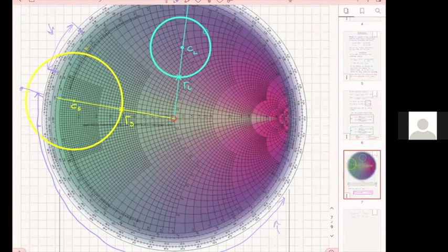Is that clear the way I described it, or was it not? Well, from 0.3 to 0.6 is the second stub, right? Yes, the long one. The first stub is 0.1. Longer lengths travel faster around the Smith chart. Longer physical lengths travel faster around the Smith chart when we change frequency. Shorter physical lengths travel less on the Smith chart when we change frequency.